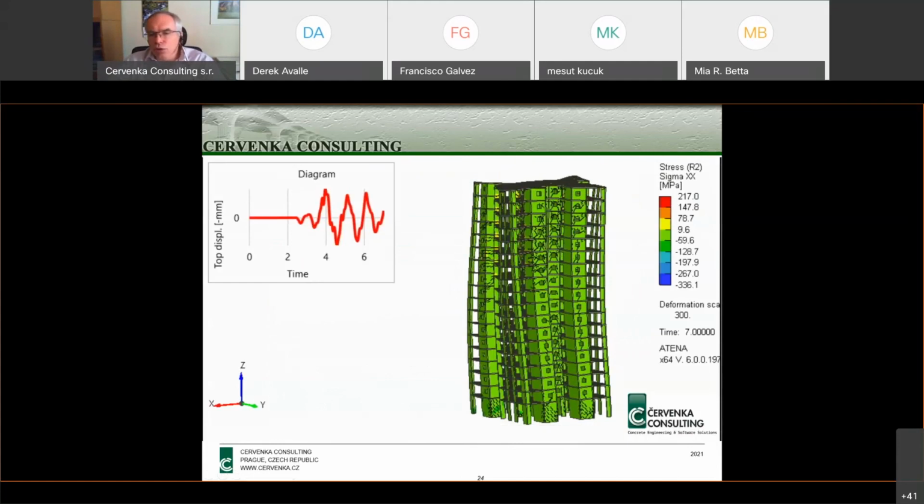Later on I will show you how this is being done. And the reinforcement is, of course, in this case, we do not model each individual bar. This would be really too complex a model. So the reinforcement is considered as special layers of these shell elements.